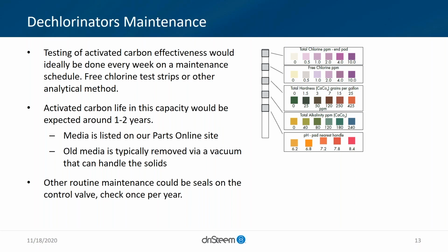Other routine maintenance would be understanding if the seals on that control valve are leaking by, just like a ball valve or a butterfly valve. You check the seals and make sure there's no bypass. Similar thing in this valve. Recommended check once per year.